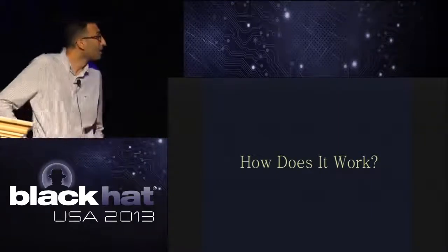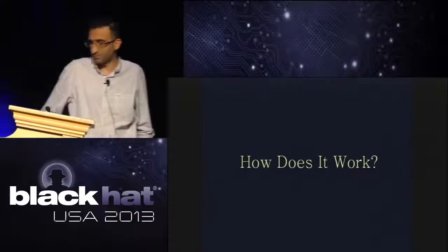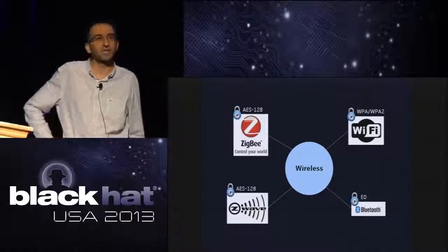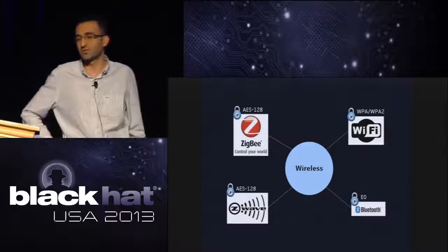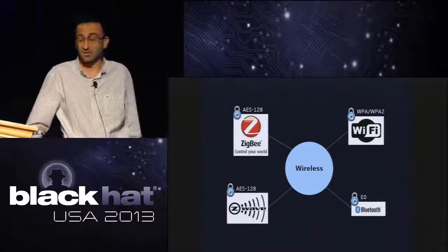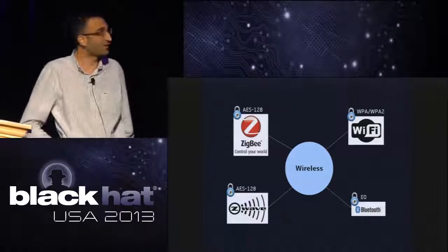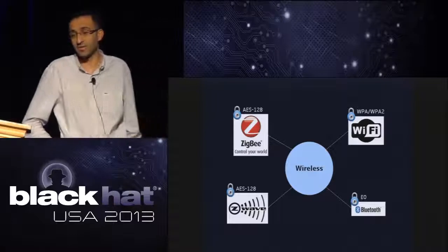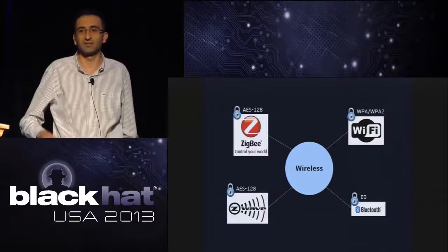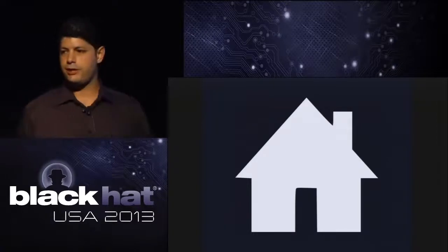Thank you. Okay, so we will look into the main components of a home automation system. First of all, we have the communication protocols. Most of today's home automation systems are based on wireless communication. Among them, the Z-Wave and Zigbee protocols are the dominant ones. This is mostly because they can operate in the sub-gigahertz frequency range, which has better penetration into building walls.